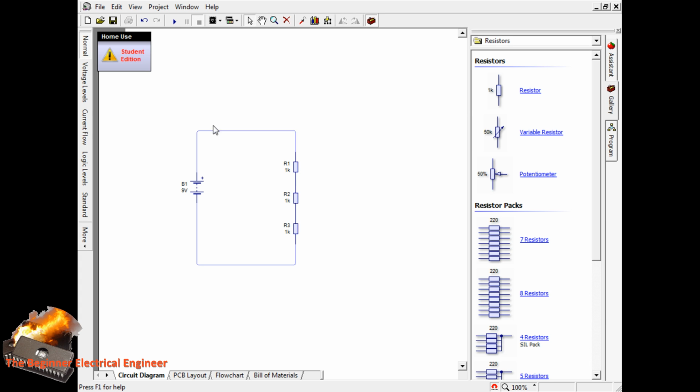Now, the easiest way to demonstrate this is through Circuit Wizard or another SPICE program of your choice. As you can see, the current going through this one is 3 milliamps, but that's not important when we're looking at the voltage law. But what we are looking at is at each side of the resistor, it drops by 3 volts. 3 and 0 volts.